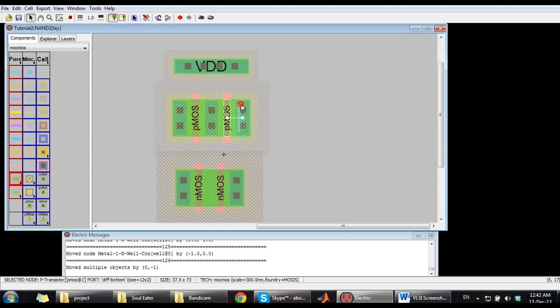Okay, now what we need to do is connect the transistors to the rails. You go to the outermost right P active, left click it so that it's highlighted, and then right click it to start the wire and connect it to the N-well. You'll see a blue connection wire. This is a metal 1 layer arc connector or a wire connector. You go to the leftmost P active and connect it to the VDD in the same way.